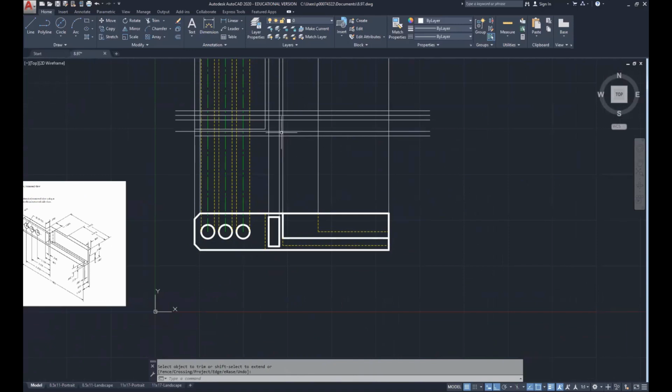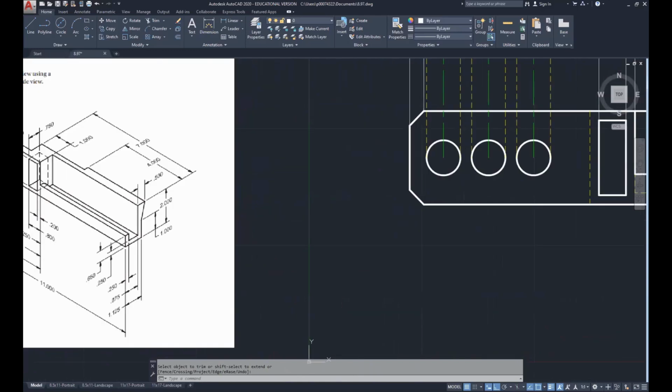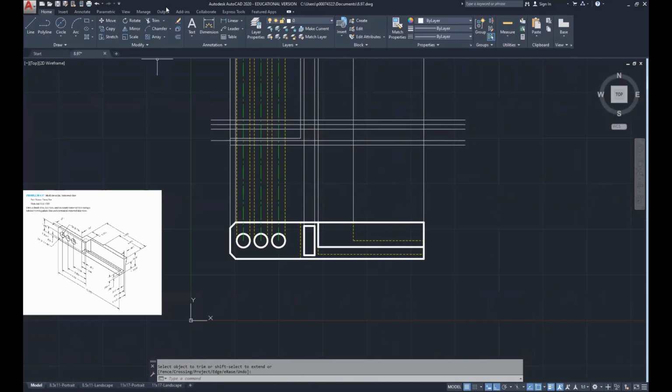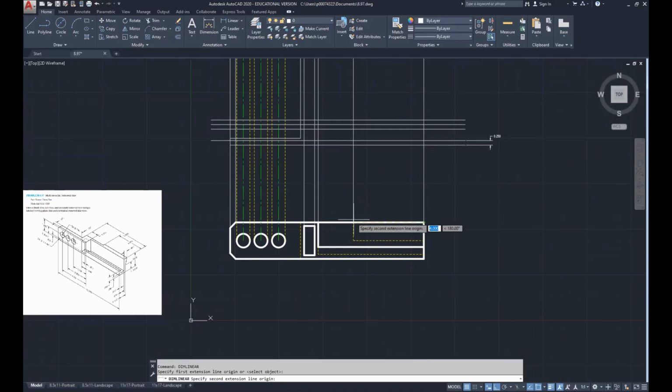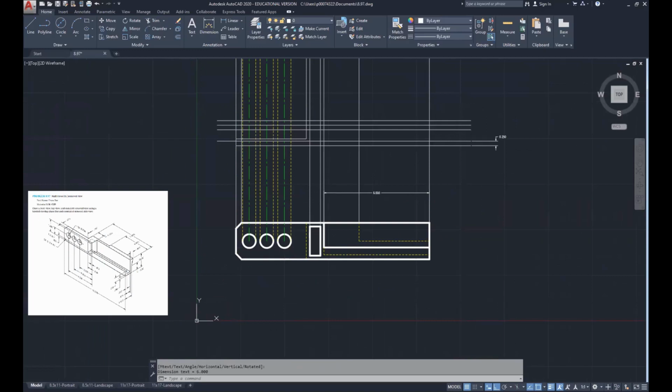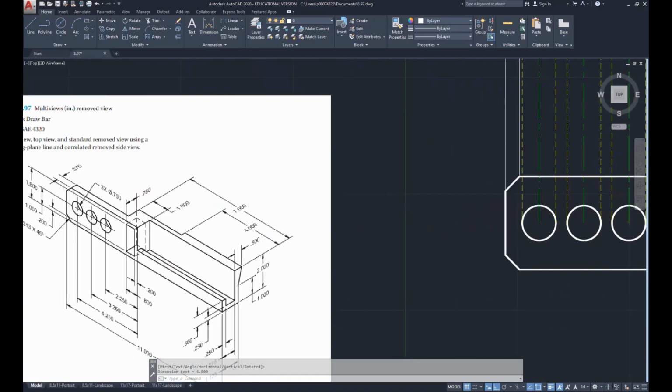Let's go ahead and establish with this line here. This is going to be our distance from here to there, which was 0.25. I'm going to go ahead and use the dimension tool to demonstrate from here to there. And the length of this is going to go from here to here. You can see the projected line. That's our 6. That we don't actually have dimensioned, but you can see here from 7 minus 1 would give us 6. That's where that surface begins.